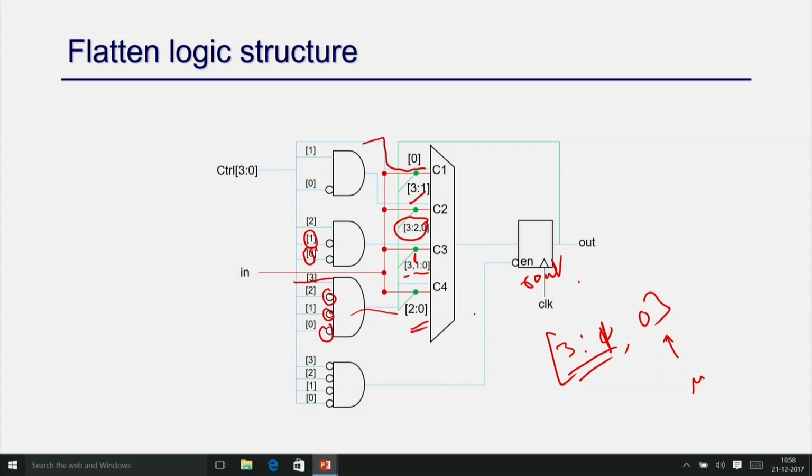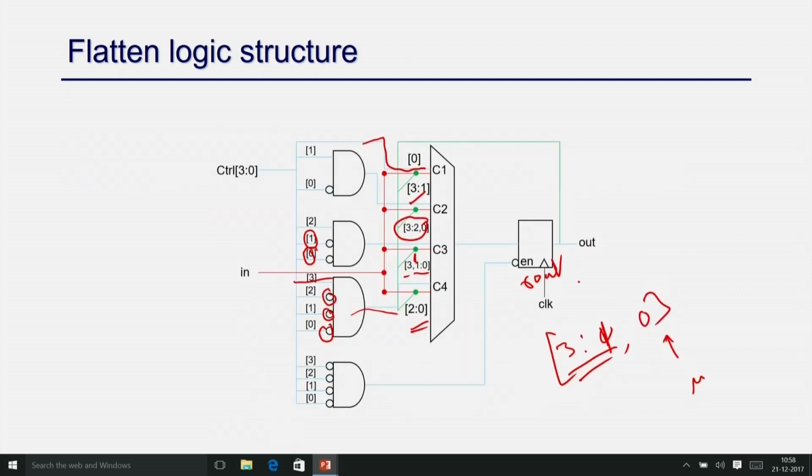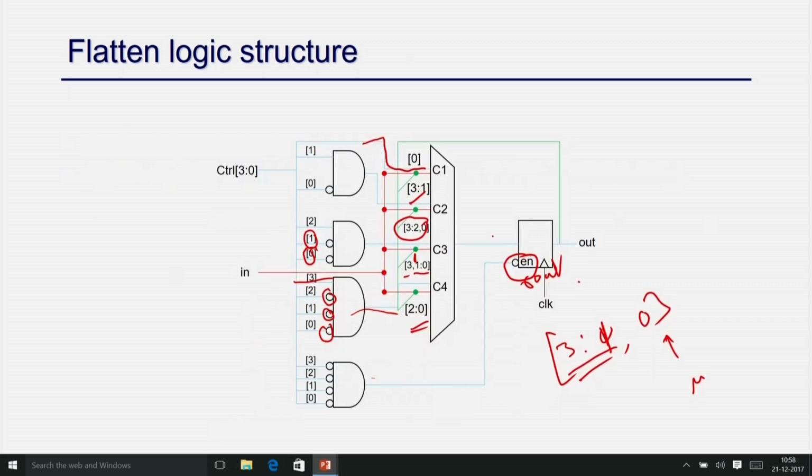So, bits 0 to 2 I am going to take from this R out, and the third bit I am going to take as the input, right. And there will be a fourth case as well, where all of them are 0. Then you just copy, you are not going to update this data if this becomes the enable of the design, right. So, this is the implementation of this circuit in hardware, and you can understand that big adders are happening here, right.